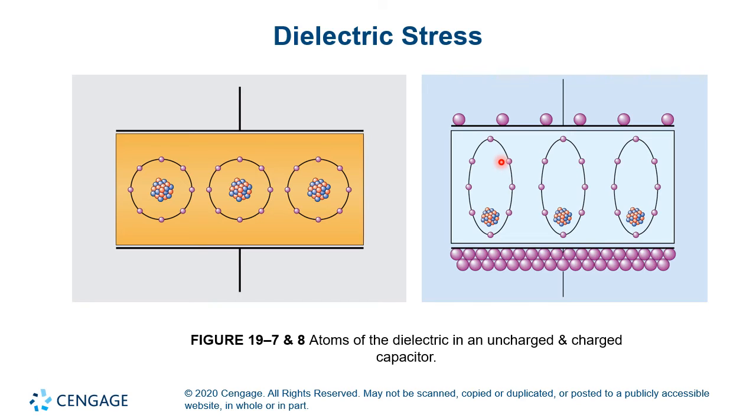Right? So we're storing our charge in two forms. One, the form of this electrostatic charge of moved electrons, and the other one in these stretched or distorted atoms. When the capacitor is discharged, all this essentially comes back to this original format over here.